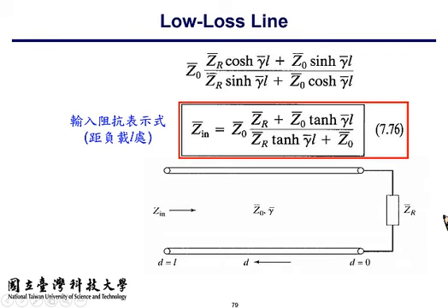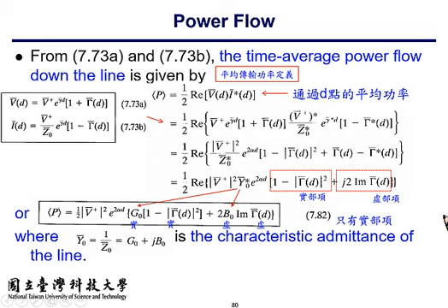So it's not a very difficult result, but you need to know this relationship. Okay? So take a few looks at the equation and get a bit of an impression of it. That is, once you have Z0, Z_R, gamma L, an understanding of the transmission line loss and the load impedance, after a section of transmission line, your input impedance can be described correctly. As long as you know what your load is, how far you travel on the transmission line, the loss constant alpha and the phase constant beta, you can write it out, okay? Alright, and the last thing that we need to describe is the power flow.